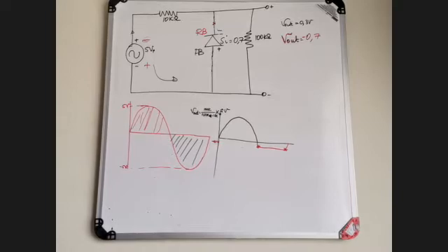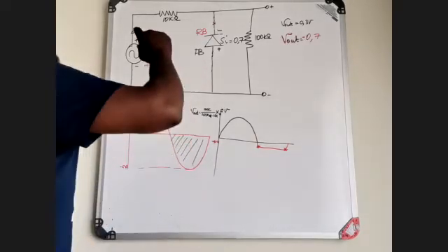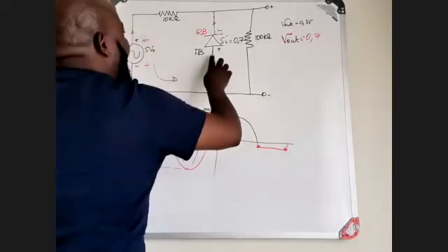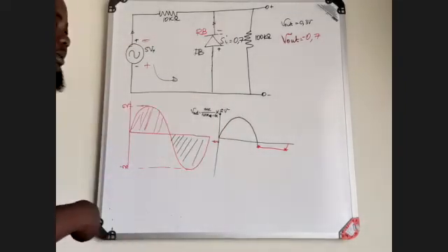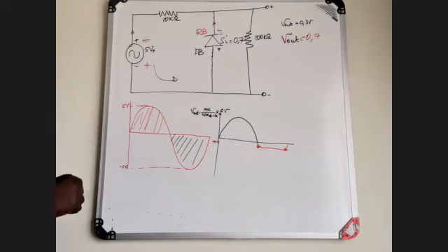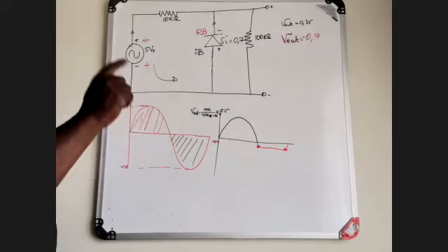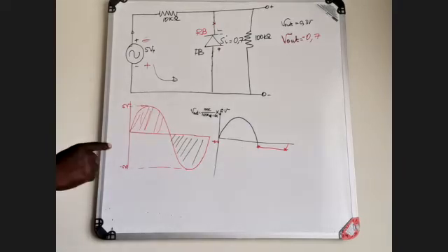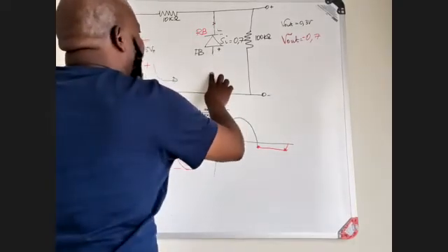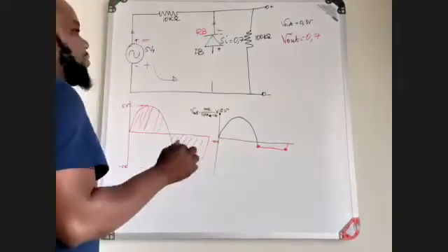I want this voltage to be a little bit higher than 0.7 volts, which means I can go and bias the voltage. When I bias the voltage, I need to bias the voltage connected in series with the limiter. But the connection is very important.